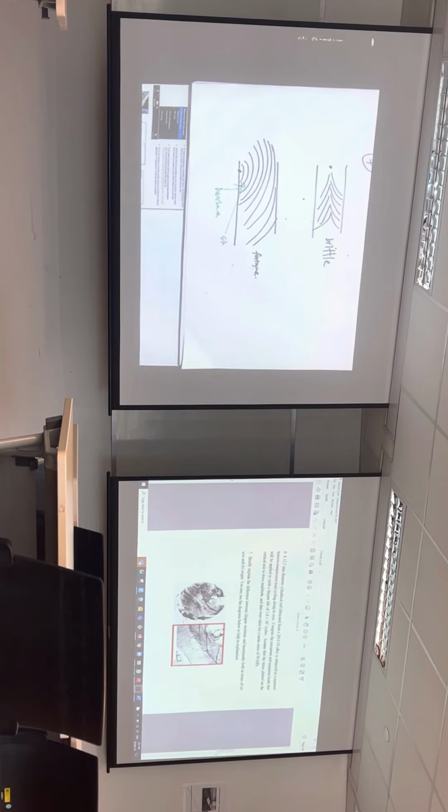As an example, when a plane takes off, if you look at the wings, when the plane takes off or lands, that's one major cycle. Maybe you create a beach mark. But during flight, where there is just vibration, those are the ones that create striations. So beach marks deal with far bigger loading that causes bigger advancement. The beach mark is a line, and striation is a lot of lines.